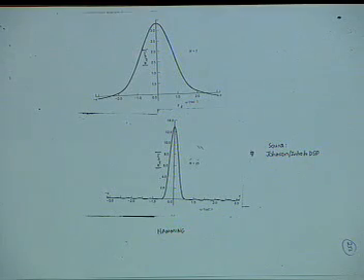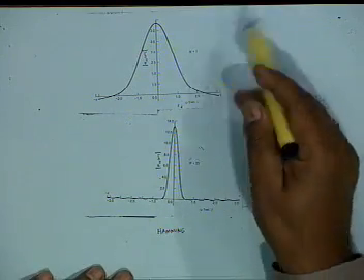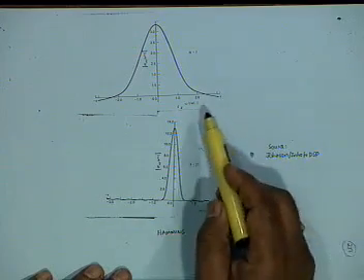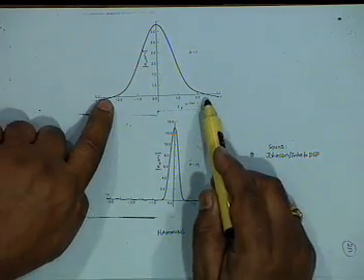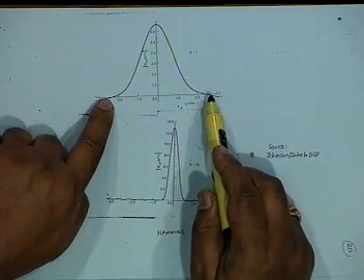And the effect of increasing the length of the window is very similar to the Hann window, except that Hamming allows for a little more reduction in side lobe height. This is for N equal to 7, and you notice that the main lobe width has increased beyond 4 radians.